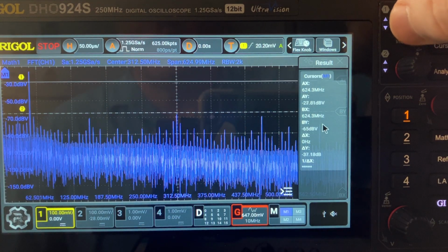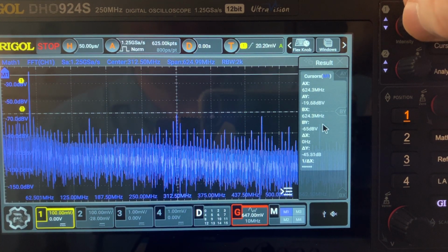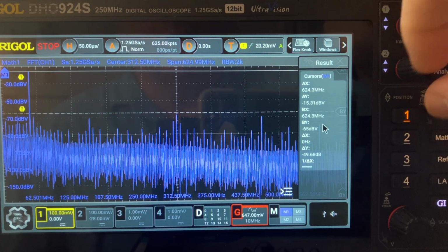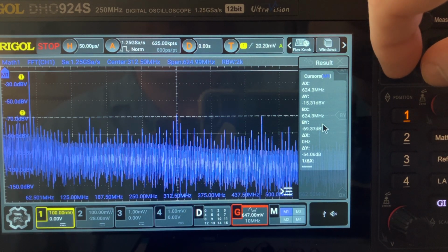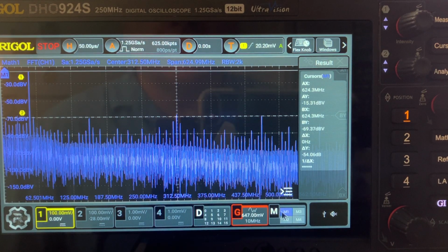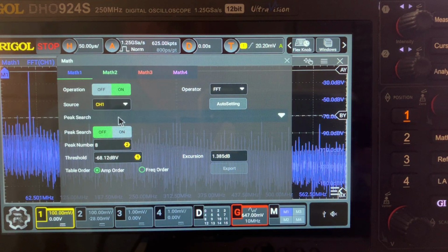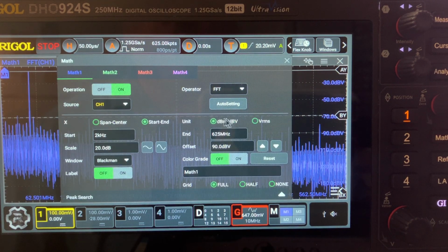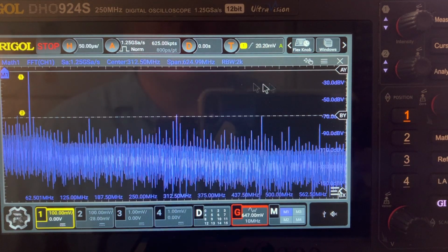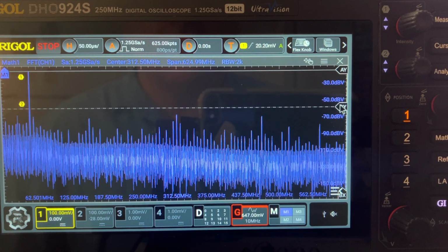We could look differently with this. You have cursor. You could put the cursor on the top component, and you could search graphically. Well, let's do something. I don't want to have the display. Let's change to none. Label is off already, but now it's easier to look at. So let's go back to the cursor. You could drag it here.